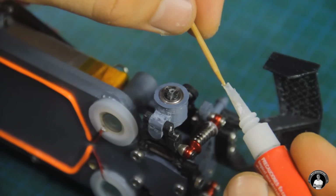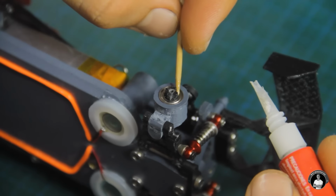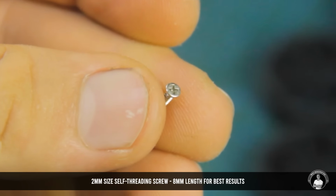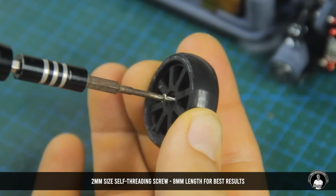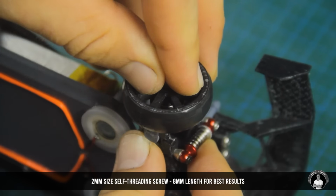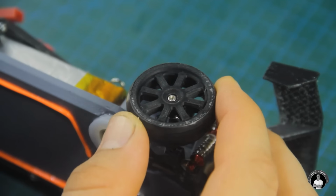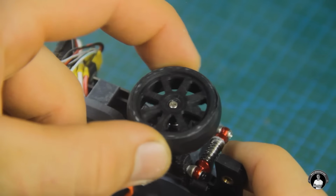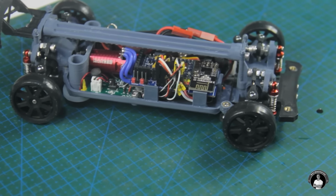But before we attach the wheels, adding a bit of super glue to the inner edges of the bearings will help prevent axle wobble once the wheels are on. So with the locking feature of the crosses, we can pop on the wheels and secure them from falling off with some small screws. Unlike what you see, I do recommend using ones that are twice as long.